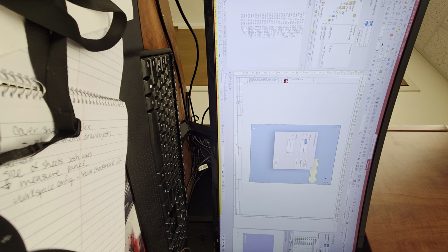Now I want you to use the relative field, as in if your starting position was a bottom left corner, now you can say I want my thing to move, let's say 3 inches in X and 5 inches in Y, as long as it fits on the sheet. And click the left button to place it. So it's using your original starting point and placing it relative, 3 to 5, as you just described. So that's 3 different ways you can place these items in a very specific location.